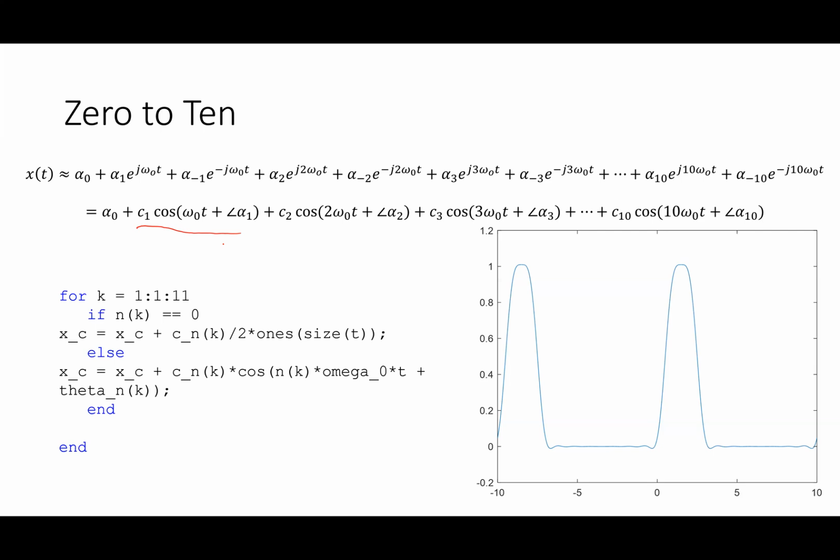But what I would call the higher frequency content kind of fills in the details. Like if you look at this guy, he looks a little bit more rounded maybe than he should, but otherwise his basic shape looks the same. So sometimes the way I think about this, the higher harmonics are basically the fine details, if you will. They don't contain a lot of, quote, information in my mind. They contain maybe some important information to make this guy look just right, but they're just details. They're not all that significant for getting the basic idea of the waveform down. So because they don't carry as much information, they're not as important to get right, let's say.